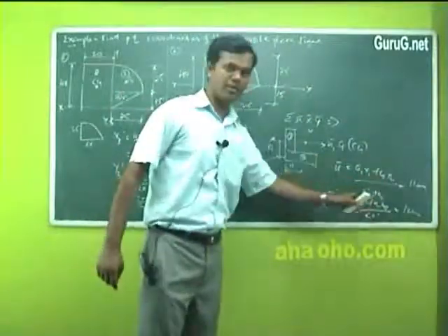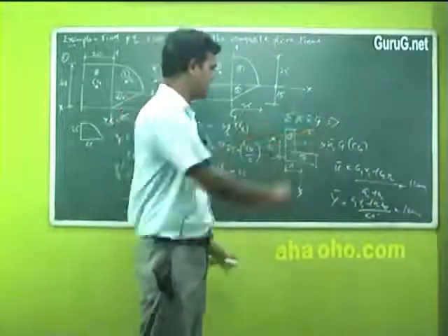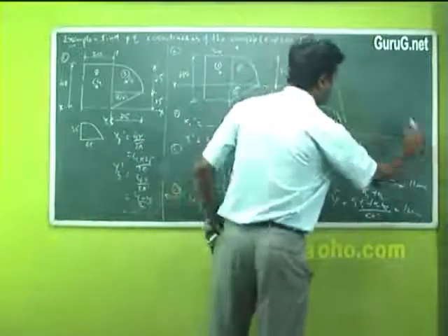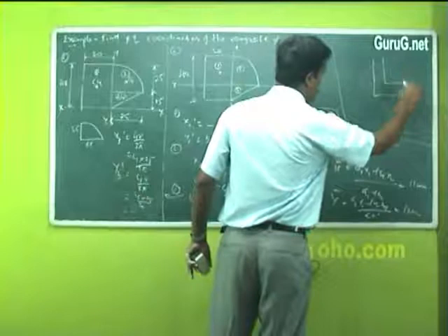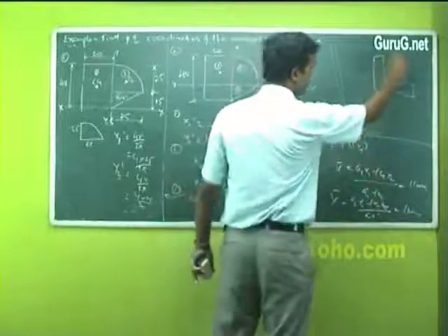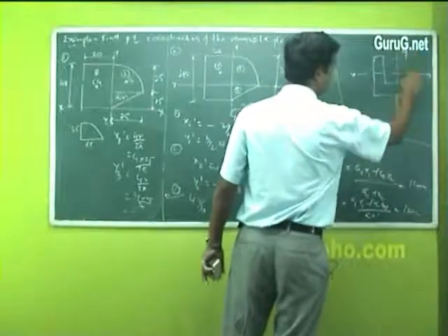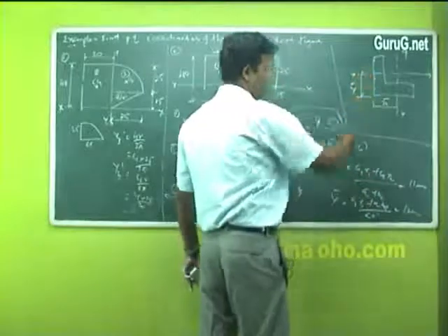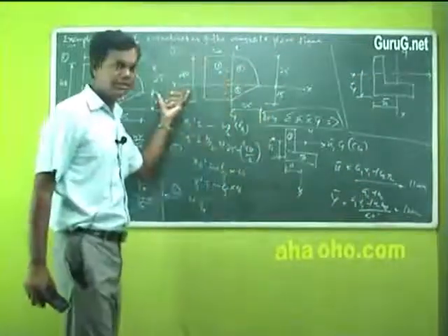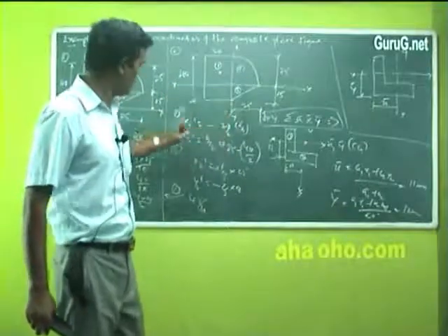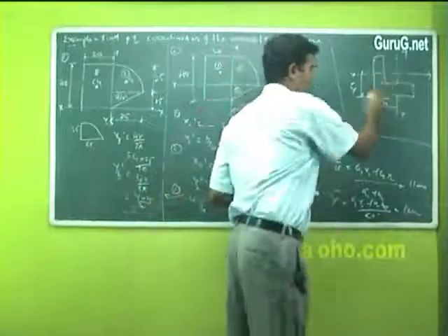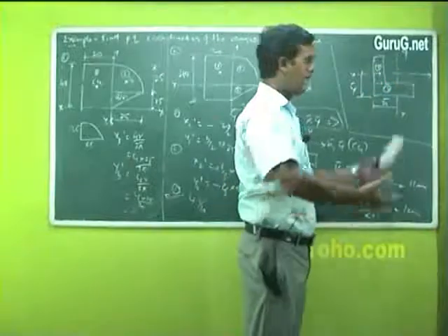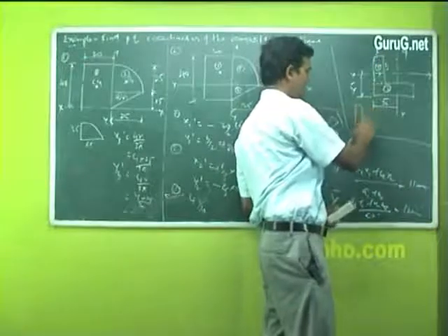After this step, with x bar and y bar, we are going to find the coordinates to find the product of inertia, Ixy. What will you do here? This particular sketch, with the values of x bar and y bar, this is your x bar value, xx, yy. Now your xx and yy are fixed. To go for the coordinates, depending on this being a rectangle, first rectangle, second rectangle, if I want to find the center of this rectangle, what are the rules? This is L and this is B.